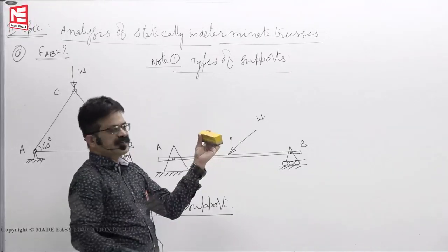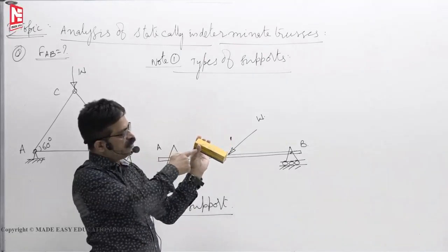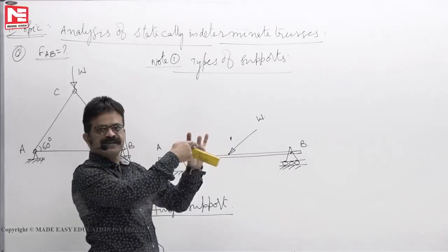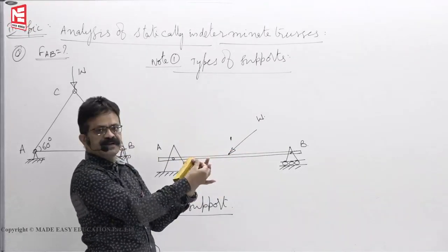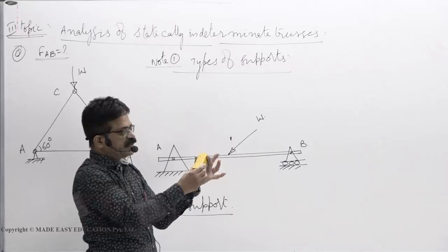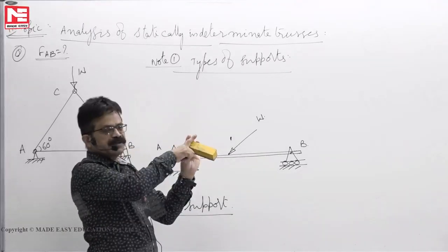So two will be there, let us say. You take a drill bit, make a hole into the finger, into the duster, into the finger. Insert one nut, bolt, keep tighten the nut. That connection we call it as a hinge connection. Now you see there is only one bolt here.